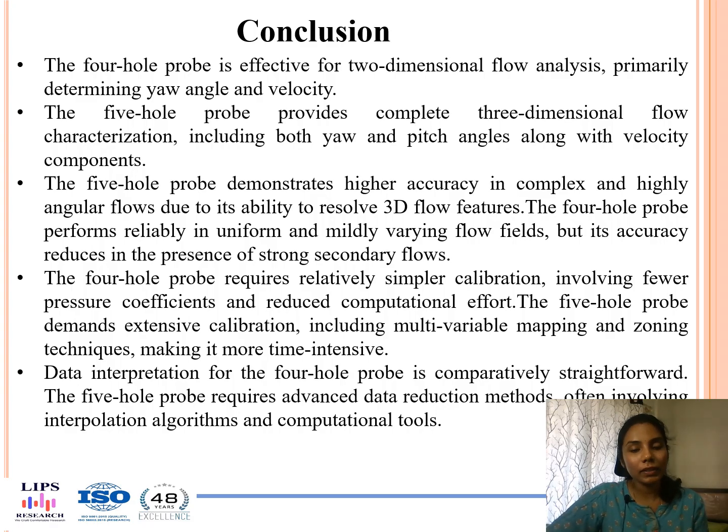Data interpretation is also more straightforward in the four-hole flow analyzer. So in short, the four-hole flow analyzer is simpler and suitable for basic flow analysis, while the five-hole flow analyzer will help us solve more complex problems. It provides high accuracy and complete three-dimensional flow information, especially in challenging flow conditions.